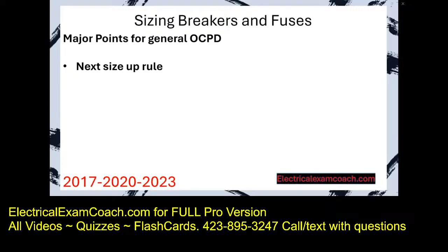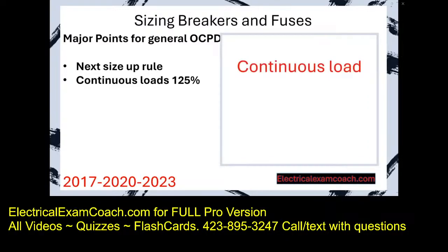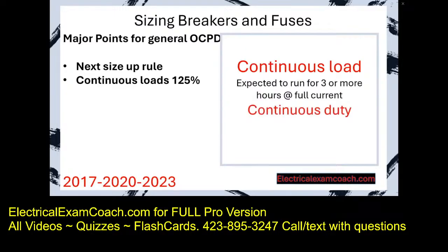The next major point is going to be continuous loads at 125%. There are two different names that you may see: continuous load or continuous duty. A continuous load is defined as expected to run for 3 or more hours at full current.